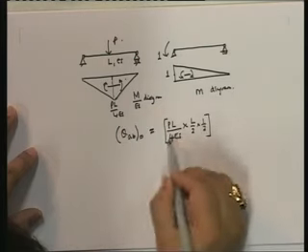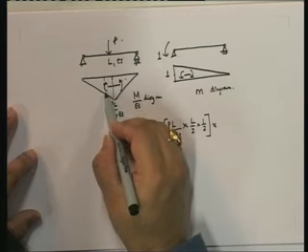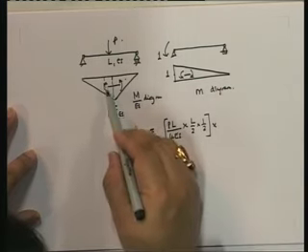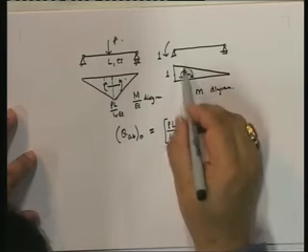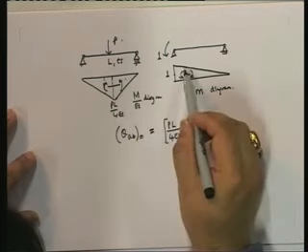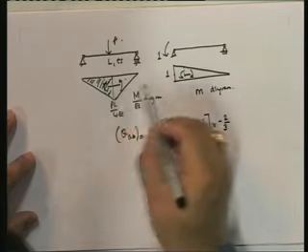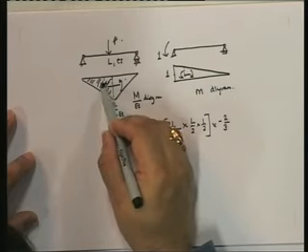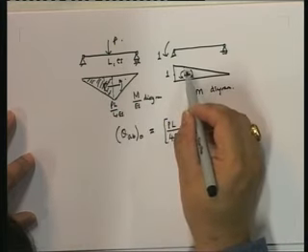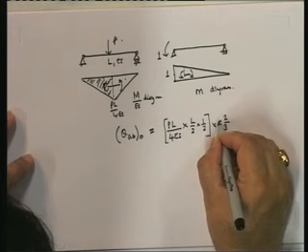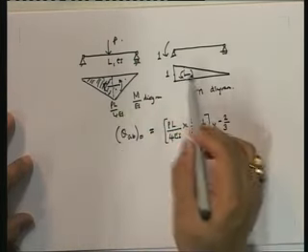And since I am taking this way as positive, this is going to be negative. The value at the centroid is minus the value at the centroid of this part. Centroid is at 2/3 of L by 2, which is 1/3 L. So if you look at 1/3 L from this side, the value is negative, because if this I consider as positive, this is negative.